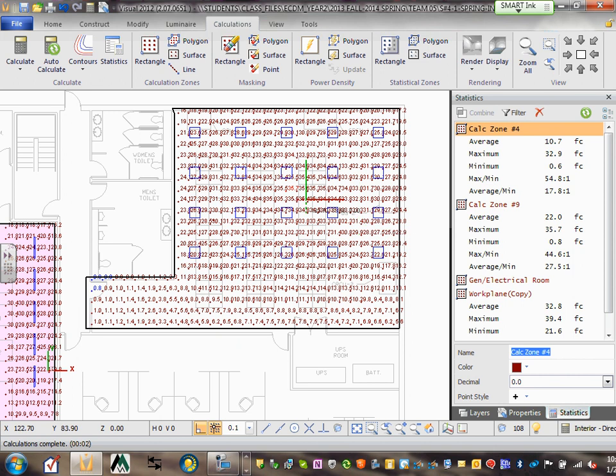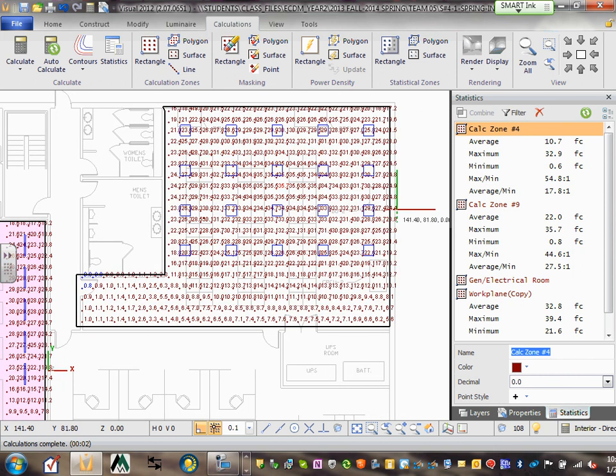The only way you can do it is to make it into two shapes. You can make one box here and do the calculation based on this box. Drop the fixture, and then do another calculation for this little area. Drop the fixture. When we drop the fixture in the calculation zone, then, like Derek, I like your idea. After you drop them here, erase the calculation zones. Now the only thing left is what? Fixtures, right? The only thing left is fixtures.